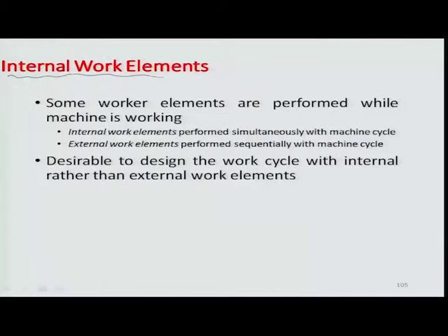So, then we can classify work elements into internal and external types. Generally it is probably a prudent idea to make more and more work elements of the internal type, and let's look at what they are. Some of the worker elements are performed while the machine is working. So you can say that the internal work elements are performed simultaneously with the machine cycle, and the external work elements are where work is performed outside the machining cycle.